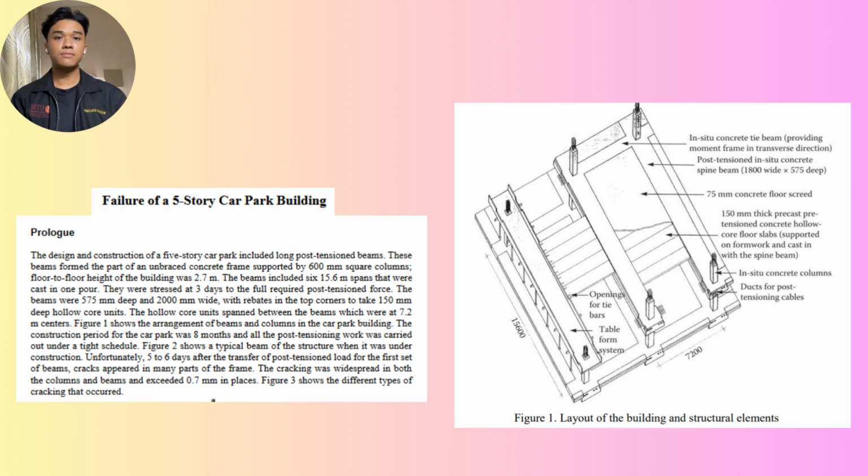After 3 days, the beams were stretched to the required force. However, about 5 to 6 days later, extensive cracking occurred throughout the structure, affecting both the columns and beams, with some cracks exceeding 0.7 mm in width. The cause of the cracking needs to be investigated.